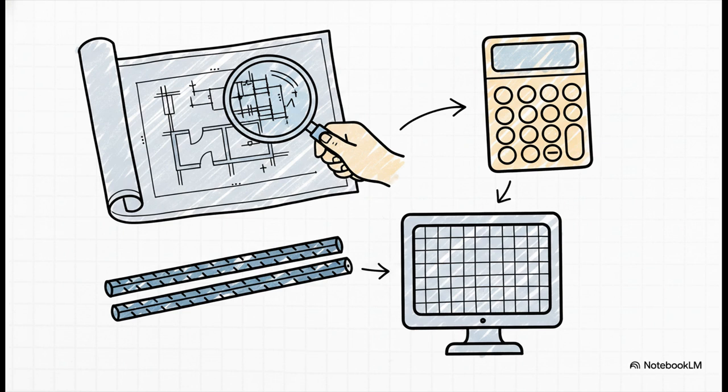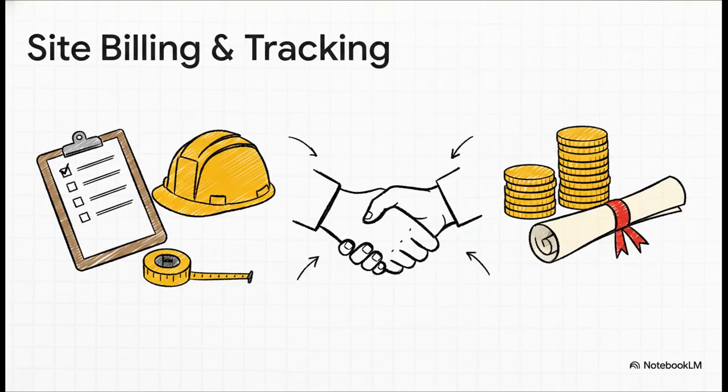And hey, these days we rely heavily on software like Microsoft Excel and specialized quantity takeoff programs to calculate area, volume, and weight metrics, because there is absolutely zero room for error here. But estimation isn't just a pre-construction thing. Once you're out there on the site, you have to perform daily or weekly physical work measurements, and this means sticking strictly to standard methods, like IS 1200 in India, for example, when you're measuring concrete, formwork, or masonry.